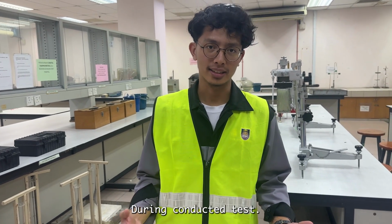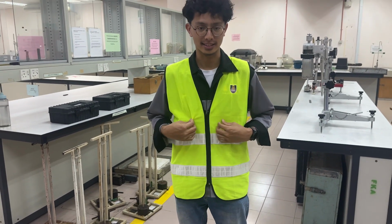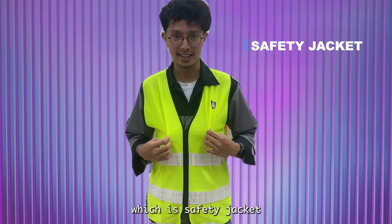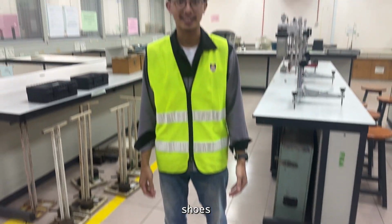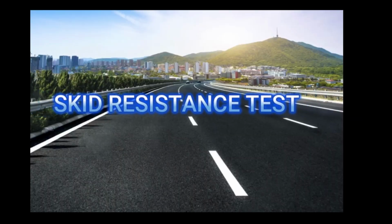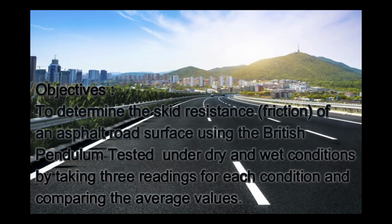During the test, we need to wear proper attire such as a safety jacket and safety shoes or sport shoes. Apparatus: British pendulum tester with basic accessories such as a brush, water spray, water, stopwatch and others. Objective: to determine the skid resistant friction of an actual road surface using the British pendulum, tested under dry and wet conditions by taking 3 readings for each condition and comparing the average values.